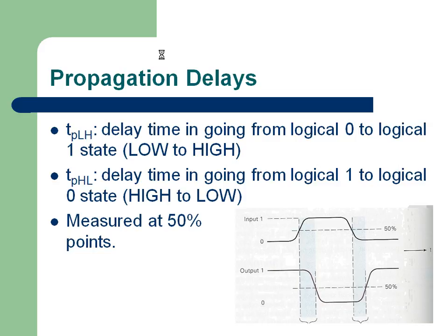I guess this definition may not be new for you, you know that the input is changing, the output is changing. An example of an inverter has been shown in the waveforms. When input to output 50% to 50% change delay is what we call the propagation delay. These definitions are with respect to output. LH and HL are with respect to output.